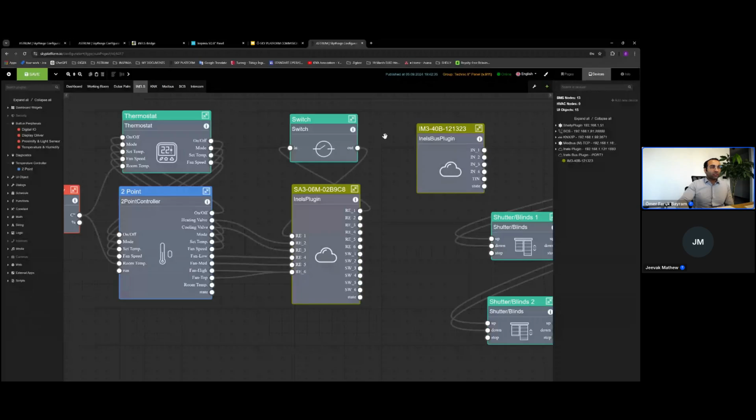After this connection, the end user will send a command, will touch, will push this button. This command will set a command to the relay input, and if the relay opens, we will see the feedback from the feedback side, the status side, and the status will go to the UI input as status.